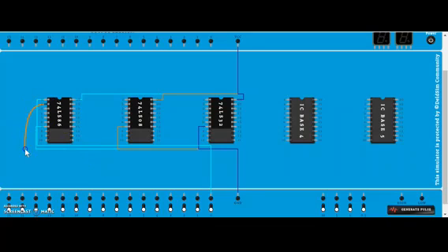The second pin I will connect to this first input, and the output of this first and second is this 3, and the third input will be from this 5 to this 2. So these are the XOR's 3 inputs 0, 1 and this 2. And now the output of XOR means this 6. This 6 we will connect to this 1, that is the sum output.